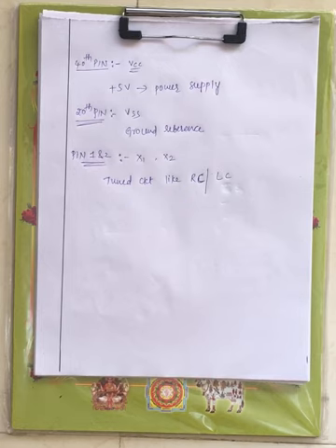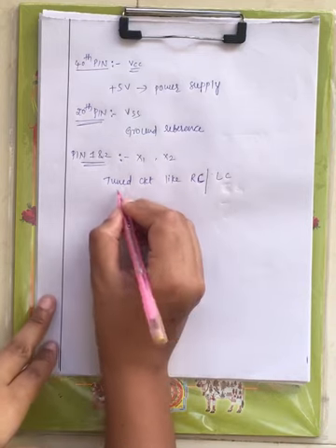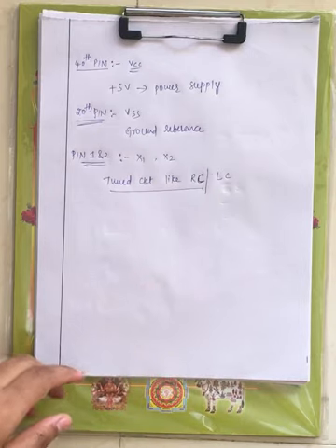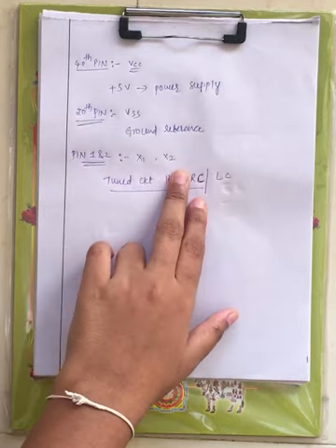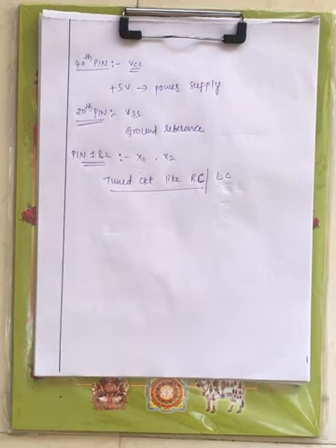In order to generate the clock signal, we are providing a tuned circuit such as RC or LC at pin number 1 and 2. Now the internal clock generator divides the oscillator frequency by 2. We are providing the tuned circuit like RC or LC, connected at pin number 1, that is X1, and pin number 2, that is X2.